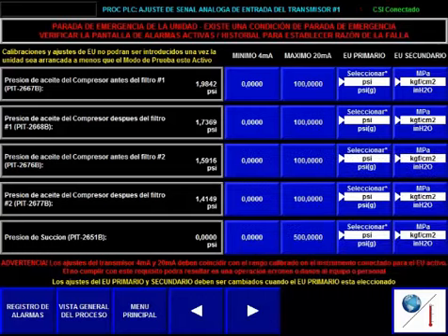Now we're going to review alarm and shutdown set points. As you can see on the first page, no alarms are indicated, so these values are for control or indication only. On this page, you can see differential pressure of the suction valve has a high alarm at 15. Yellow is alarm, red is trip. Whenever a value is in an alarm state, you'll see it flashing yellow like you see below.